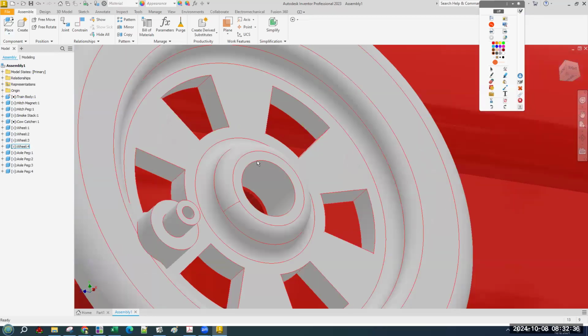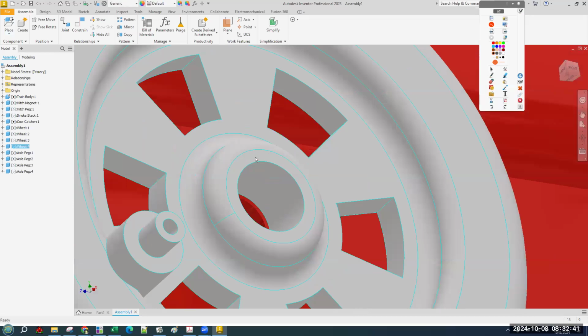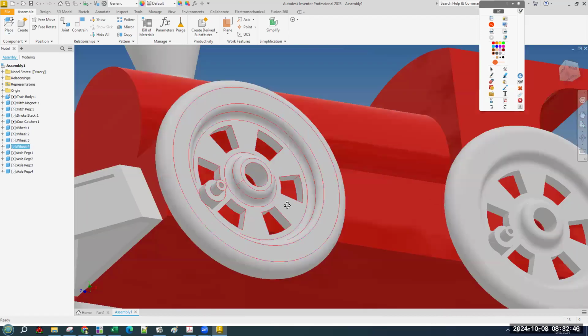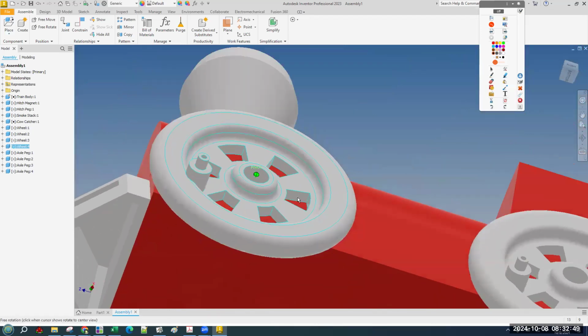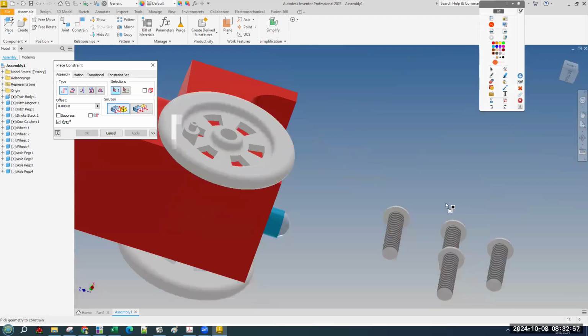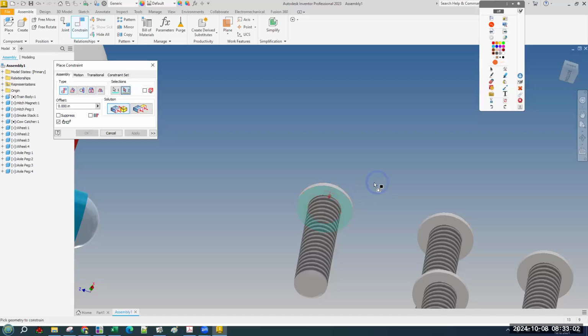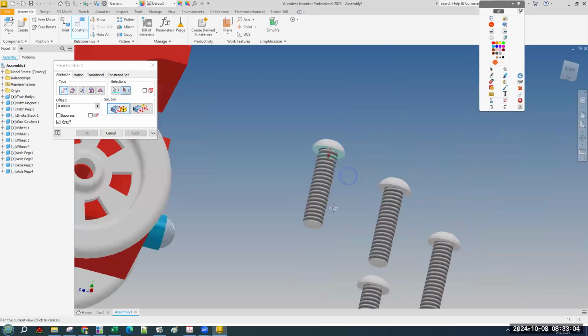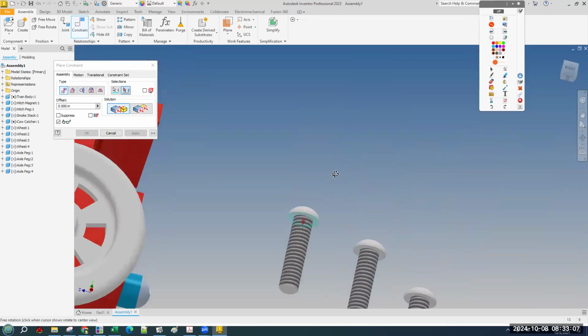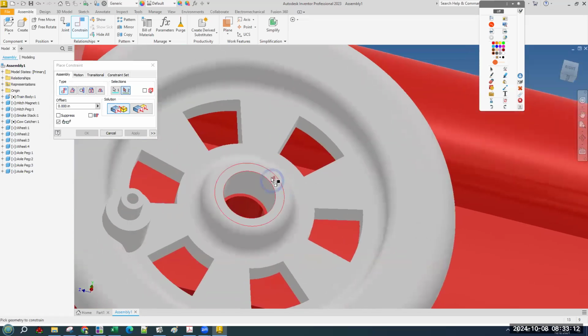It's a little finickier here because the only flat surface we have is the distance from here to here. This first ring is the only flat part that's the right height, or the right face to constrain to. Technically, this outside is too, but we're going to ignore that. So we're going to constrain, and the face we want to constrain is this under part of the peg. And that flat surface, not the green dot, needs to mate with this flat surface.